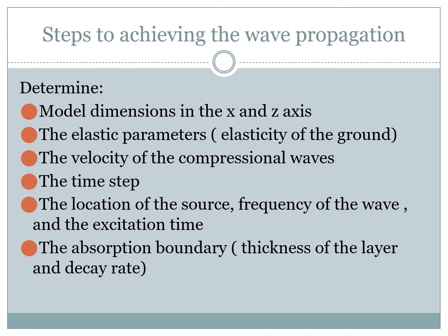Then we chose the elastic parameters, the velocity of the wave, and the time step, which is the change in time in which the governing equations are being solved in the program. Then we need to identify the location of the source, the frequency of the wave, and the excitation time. And lastly, the absorbance boundaries and the thickness of the layer.